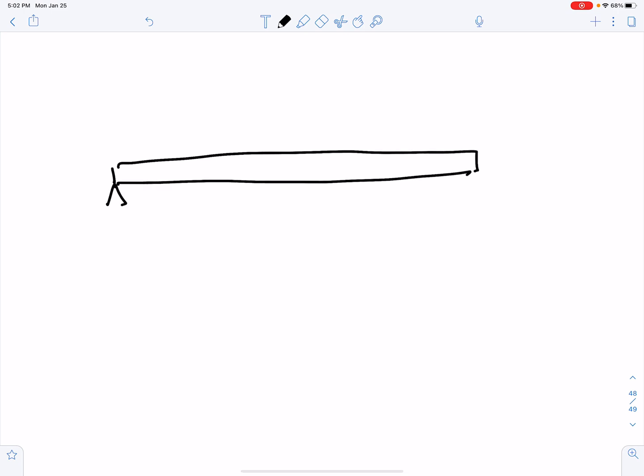And the way we're going to set this up is we'll take our beam and assume that it's pinned here. It means that it cannot go left and right, cannot go up and down in these locations. And so the only degrees of freedom that remain would be the slopes, or the rotations, that I'm going to call U1 and U2.